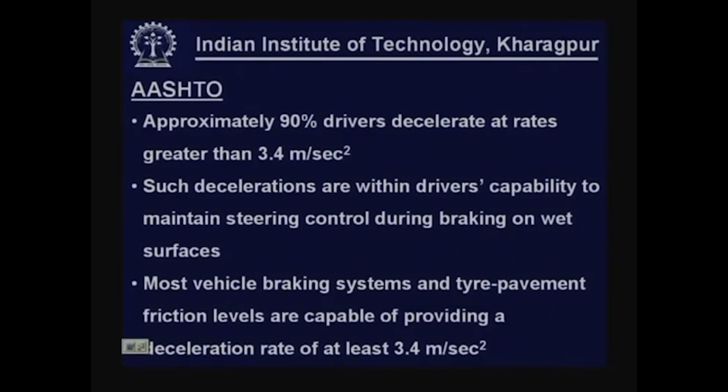Coming to the AASHTO recommendations, it is found that approximately 90% drivers, they decelerate at rates greater than 3.4 meter per second square.